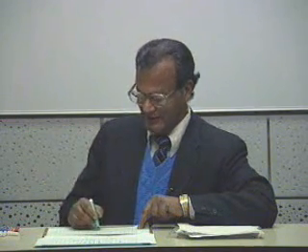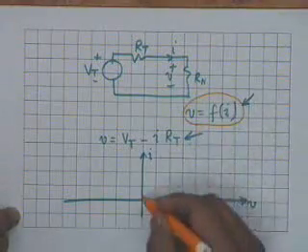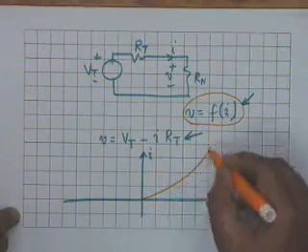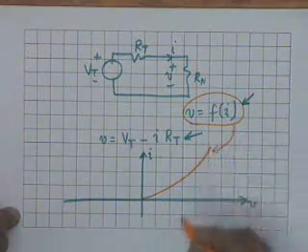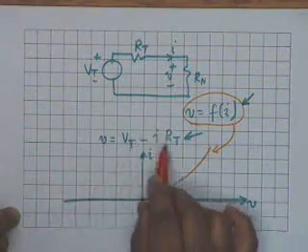Alright. So how do you solve this? You solve it graphically. That is, you make a plot of V and I. Let us say that V equal to f(I), this nonlinear relationship, is like this. And suppose small v equals Vt minus I Rt. What kind of a curve does this represent? Straight line. And this straight line is something like this,